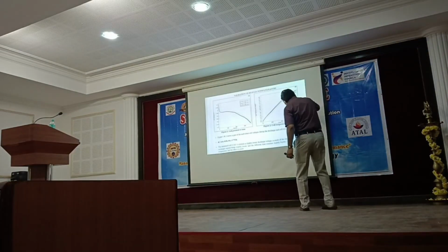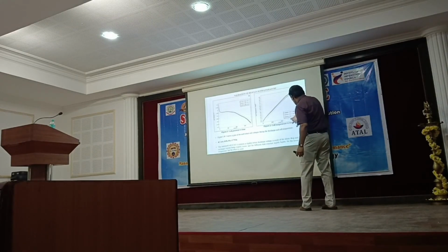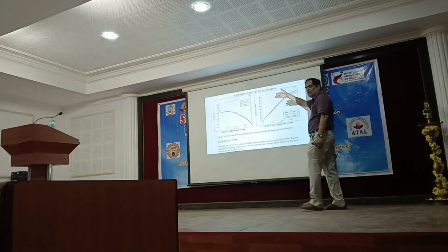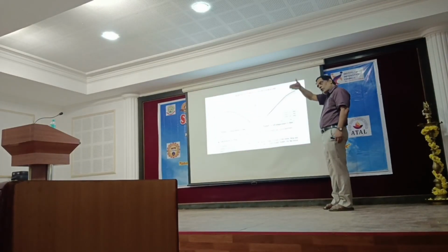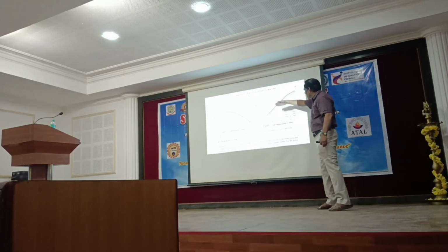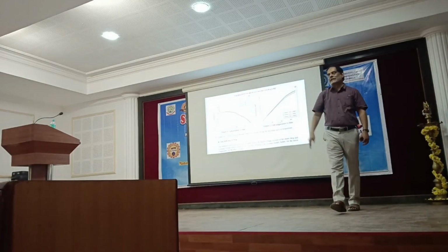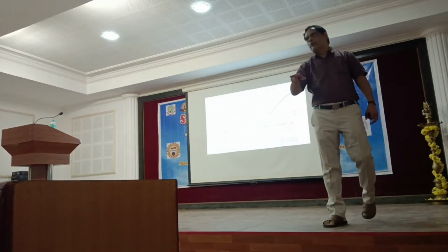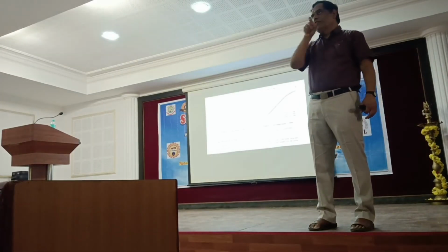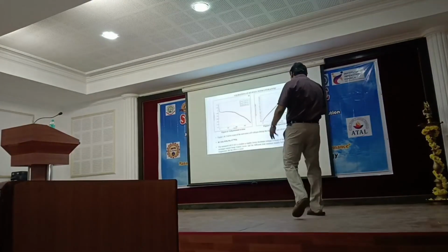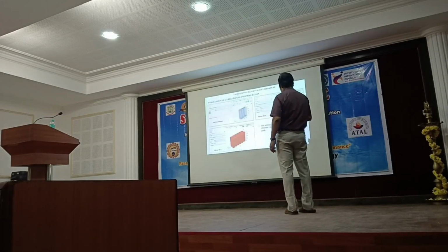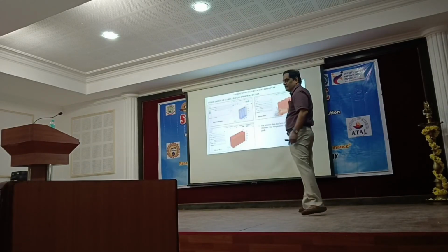Here you can see we are imposing different types of cells: cell 1, cell 2, cell 3, for different cell configurations. Since it is coupled with a thermodynamic model, I can also see the temperature rise, for shallow discharge and slope discharge. Apart from determining SOC, I can determine what the temperature rise could be. Along with it, if I have given proper cooling, I can ensure the temperature will never go beyond 50 degrees. All such things can be estimated a priori by using this software. Again, this typical cell configuration is simulated.